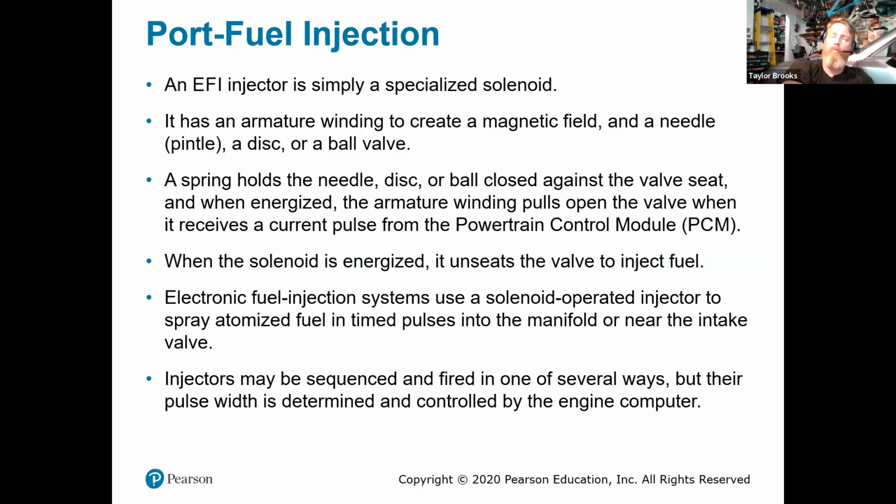Now, when we say duty cycle of a fuel injector, it's the period of time at which the injector is on, not how much fuel it sprays. Normally, when we look at a fuel injector rating, we're rating them in pounds, and that's pounds of fuel per hour. The higher the number, the more fuel flow you're going to get out of them. One of the things that you can do, I've never done it personally because it kind of wigs me out, is